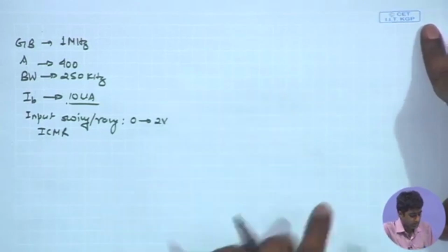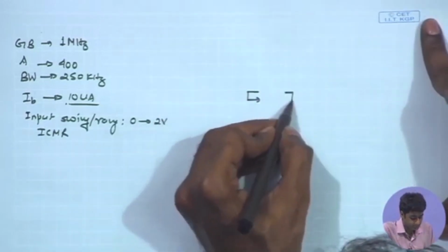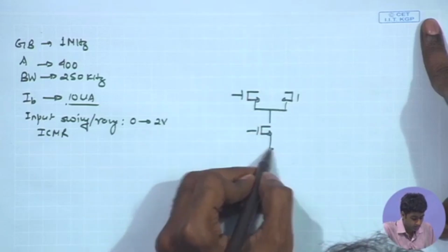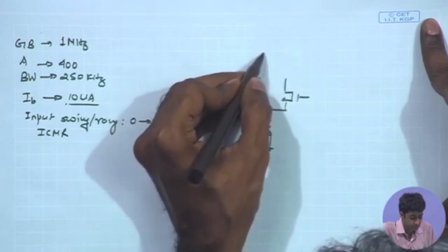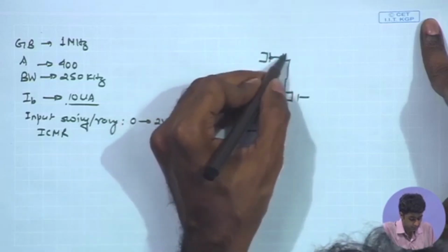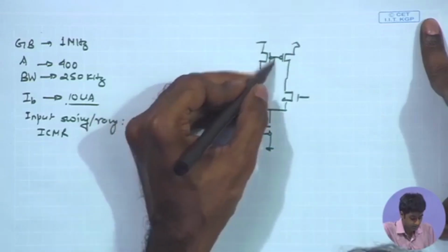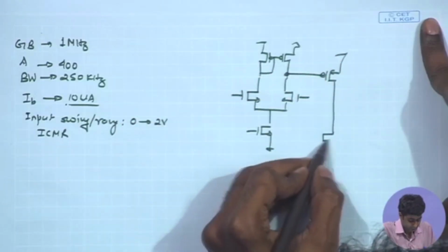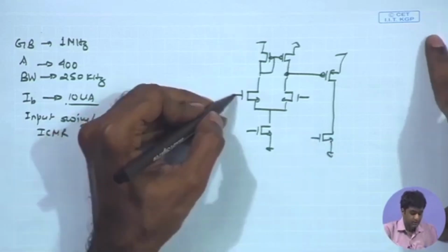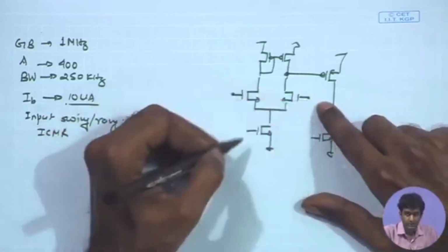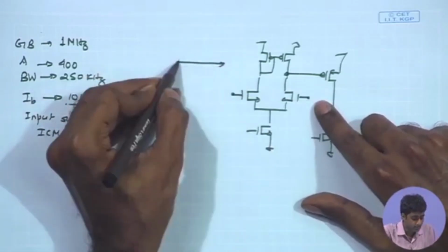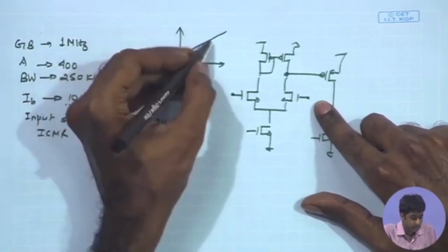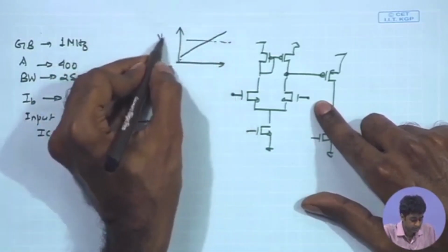So, if you look at the overall operation of the comparator that is going to be connected to our ramping circuitry and the input signal, suppose we are having the 2-stage amplifier as our comparator. Remember, the purpose is to detect the cross point when the V ramp, or the ramping signal on the capacitor, is crossing the reference signal V ref.